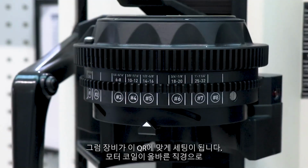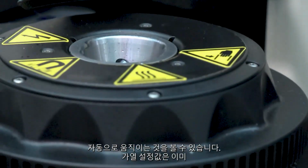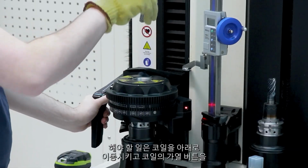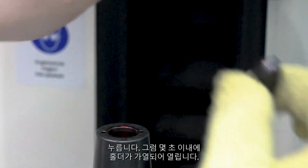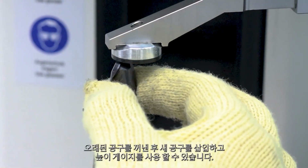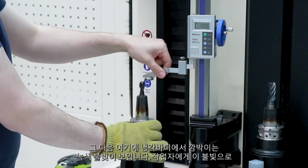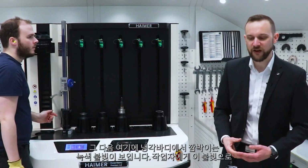You see the motorized coil moving automatically to the correct diameter. The parameters for heating are already predefined in the control. And the next thing my colleague needs to do is move down, pushing the button of the induction coil. Within a few seconds, we are heating up the holder. The bore opens. We can take out the old tool, put in the new one, and then go back to the height gauge. And then you already see here the green flashing light on the cooling body, telling the operator